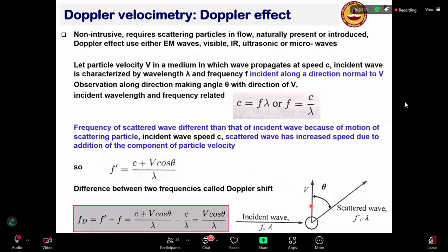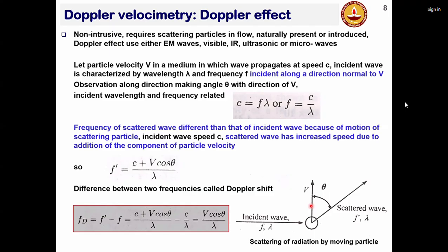Right. So that covers the fundamentals of the hot wire anemometer, how we derived the general anemometer equation, and then we talked about the constant temperature anemometer and the constant current anemometer. We also said that these anemometers can be used for fluctuating velocity measurement, where the time constant of the anemometer becomes important, and it needs to be small enough, of the order of microseconds, to measure fluctuating velocities like in turbulent flows.